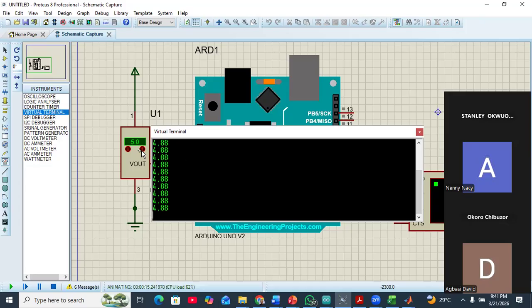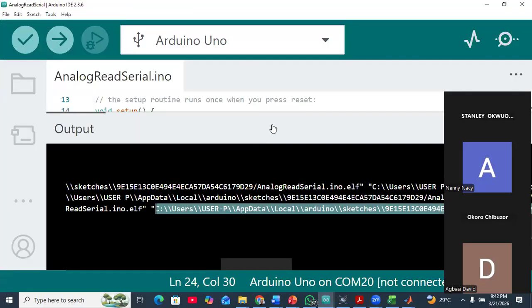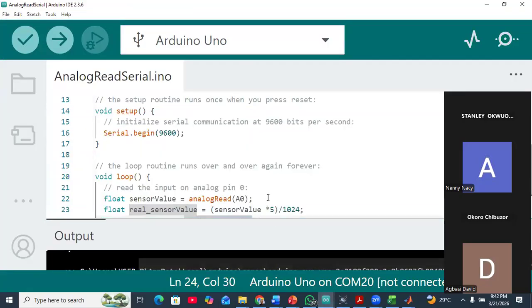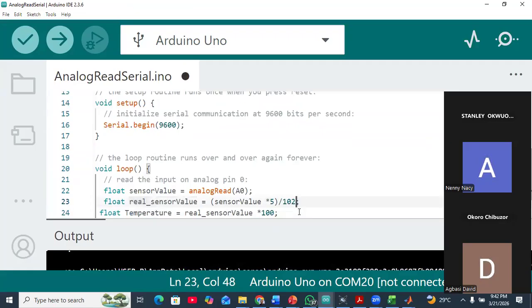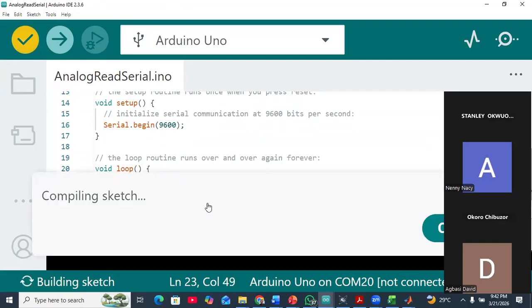Well, that's where we begin to talk about instrument accuracy. Let's see if it is consistent. You have to use software to correct it. Let's check the software. Probably I am supposed to use 1023 here and see exactly what the challenge is, because 0 to 1023 is 1024 levels. Let's see whether it will correct itself.